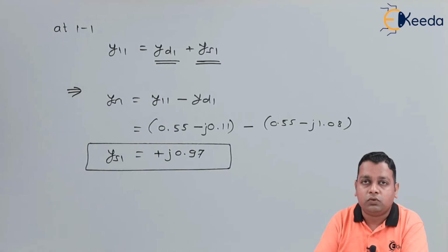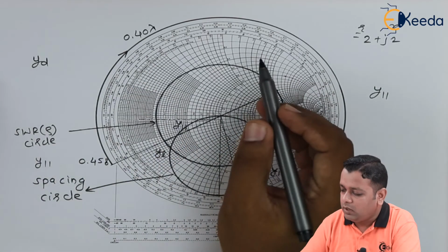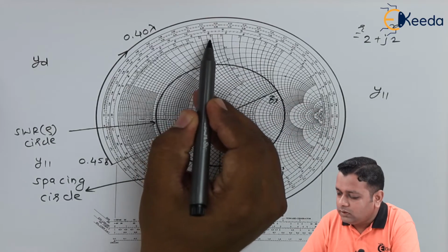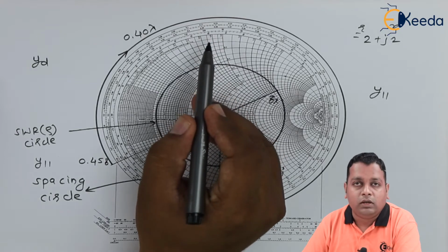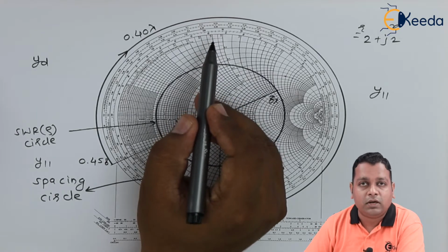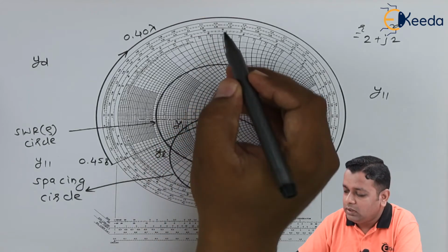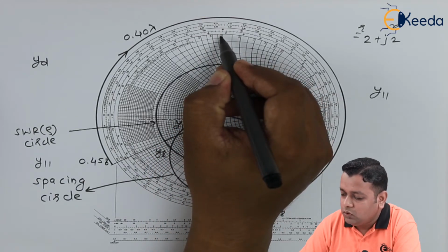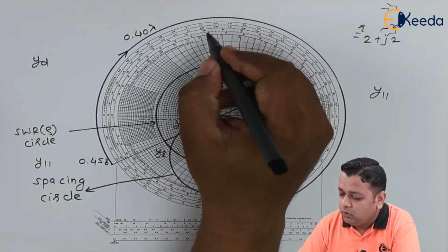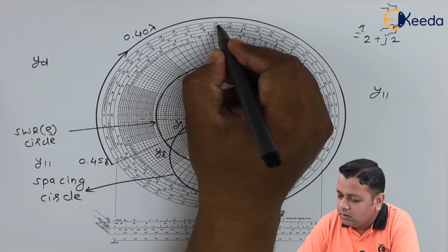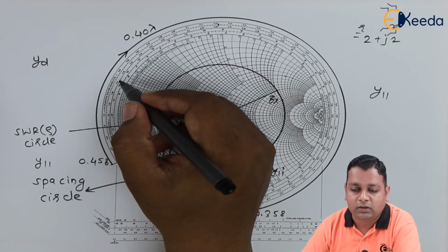Let us get it to the Smith chart here. On the Smith chart, this is 0.9 and this is 1.0, the markings for the constant reactance circles. These are the imaginary portions. So the marking for 0.97, as we are having in the positive half, onto the upper side, we get such a marking for the wavelength towards generator here.